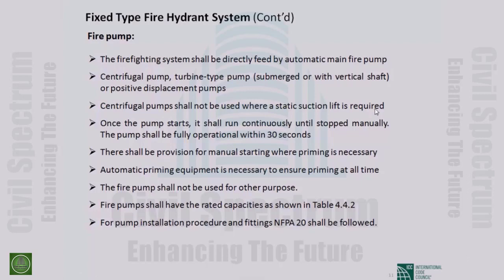In NFPA before 2016, there was no provision for that. They added this new thing after 2016, that a centrifugal pump should not work under static suction lift, though it can work.